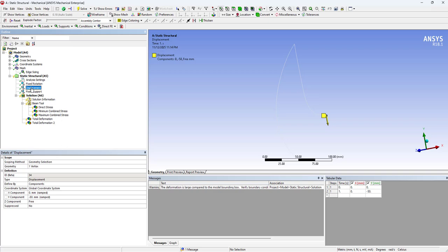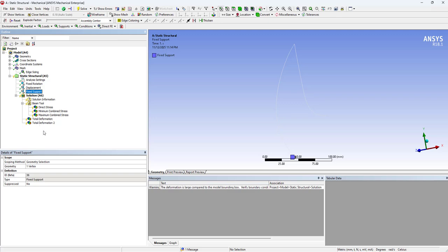So it will solve the problem for minus 5 millimeter and then calculate the deformation and change in the area using the Poisson's ratio, and after calculating the new area it will add a further 5 millimeter displacement to the problem, so the net displacement will be 10 millimeter, and will use the updated area that was calculated in the previous substep for further solution, and it will repeat this process 10 times for each substep.